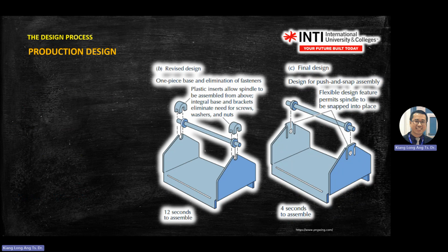So you can further simplify this design by using a spring mechanism, where you just need to cut the two slots here, because metal has spring or elastic properties. So you only need to fabricate two parts, then ask your operator just to push in the things.